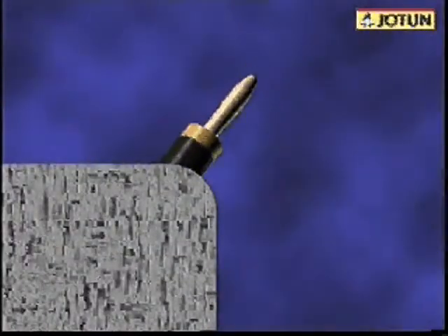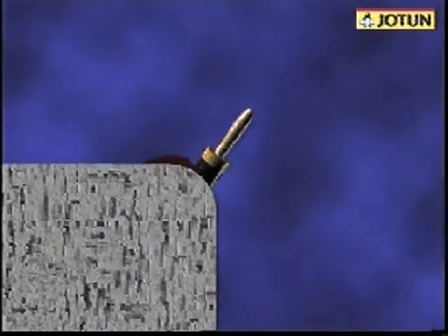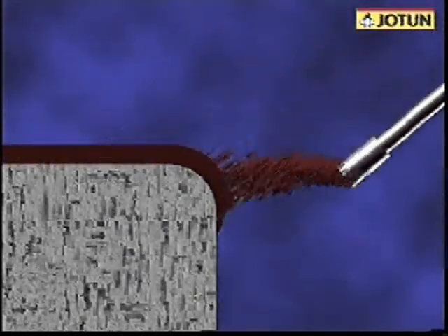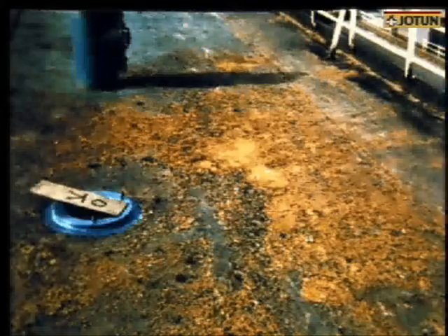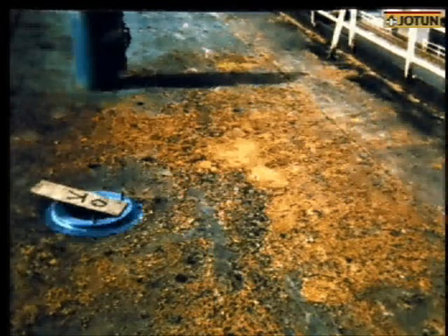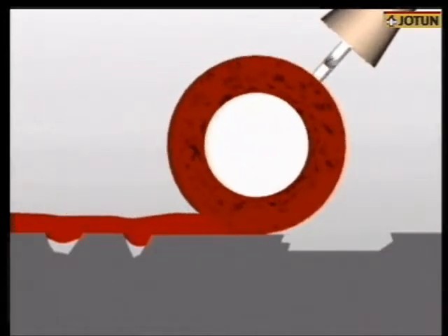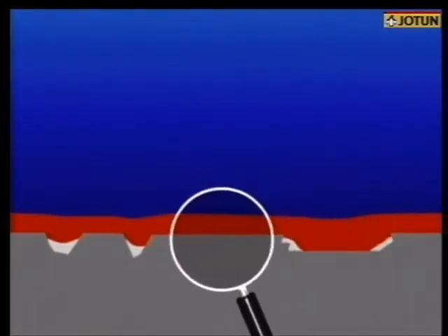Stripe coating, followed by spray application to the specified film thickness, will give an even paint film, resulting in lasting protection of the steel. Paint is applied to substrates of many different qualities. In general, one should avoid using roller application for the first coat when painting steel, particularly when the substrate is uneven, and it is definitely not recommended.